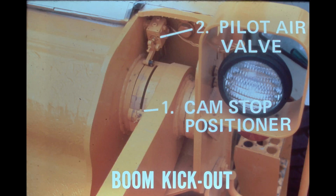A boom kickout mechanism is mounted inside the front frame at the upper end of the boom arm. As the boom is raised, the follower on the pilot air valve lever arm rides on the cam. When the boom arms reach the desired level, the cam stop positioner causes the lever arm to lift, which sends air to the boom detent release piston. The location of the stop positioner is adjustable.